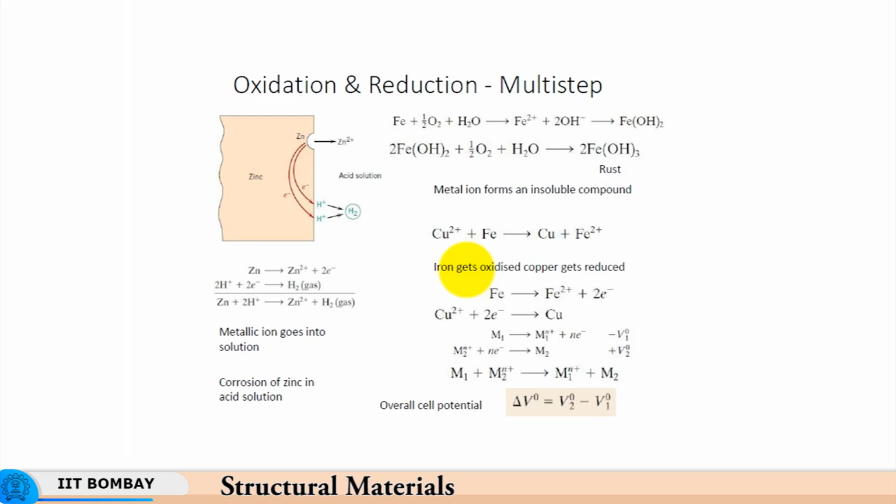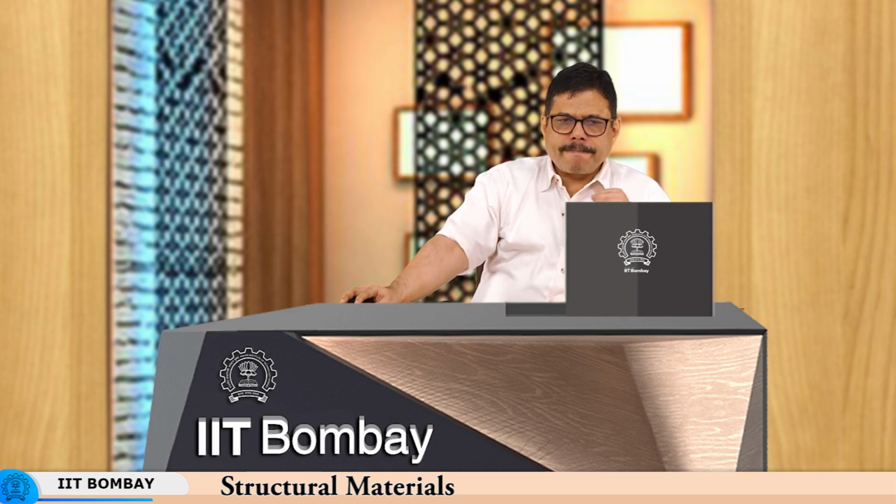Supposing the fillet radius at the change of cross section is not enough, it is too sharp, then that is enough of a reason why this region will have a stress concentration, due to which it will attract corrosive action, whereas this region with relatively lower stress will not attract so much corrosive action.